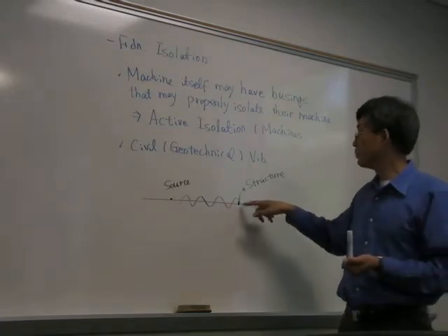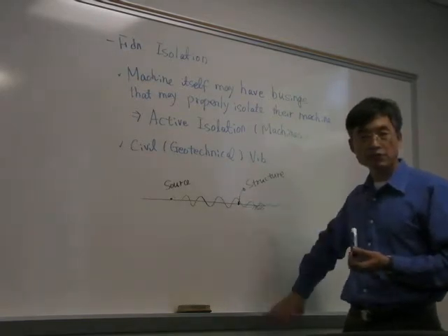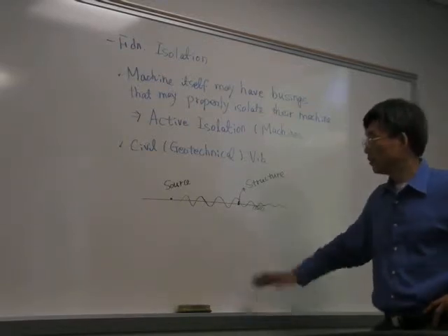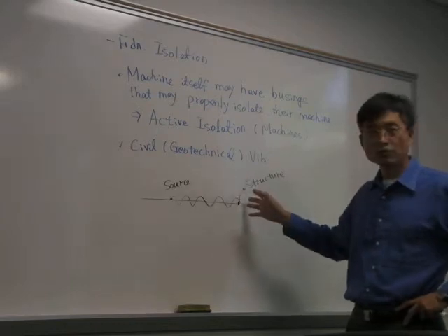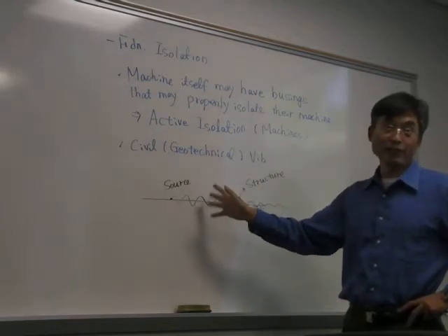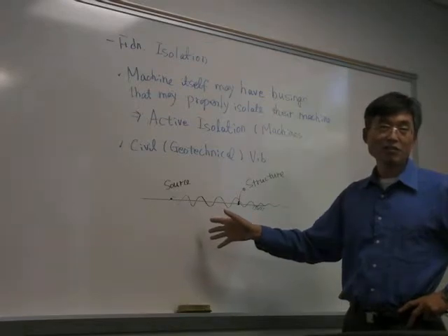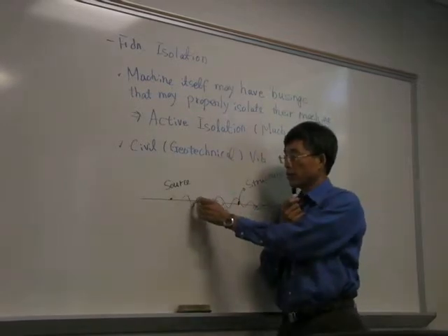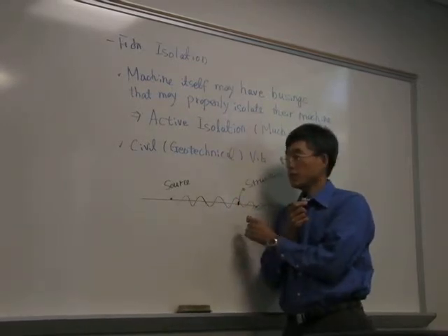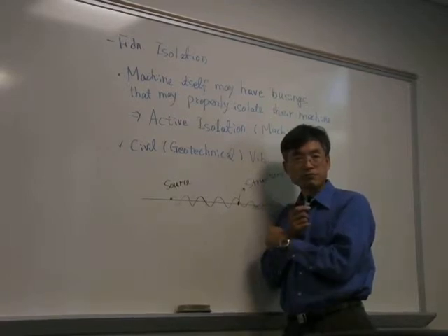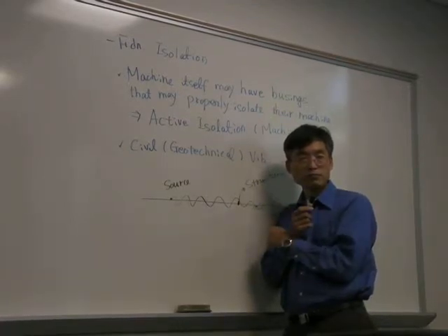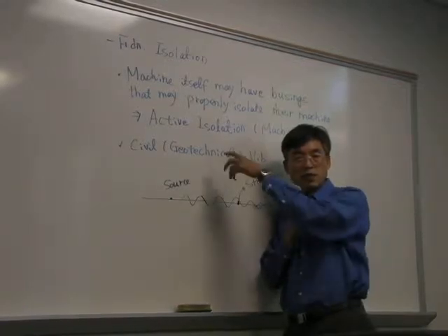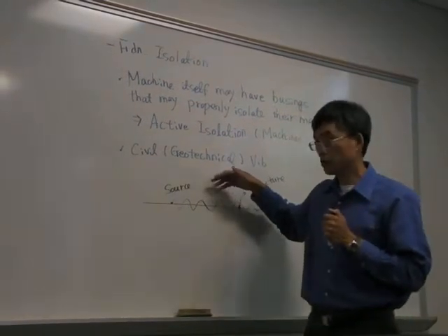Then think about how we can reduce the vibration in here. Have a medium between it, like around it. Somewhere in between those two spots, we got to put something, right? And think about the practical technique or practical means that we can put somewhere here and it may effectively cut down the vibration. Different types of soil. Yeah, maybe a pile. Piles are also actually used.